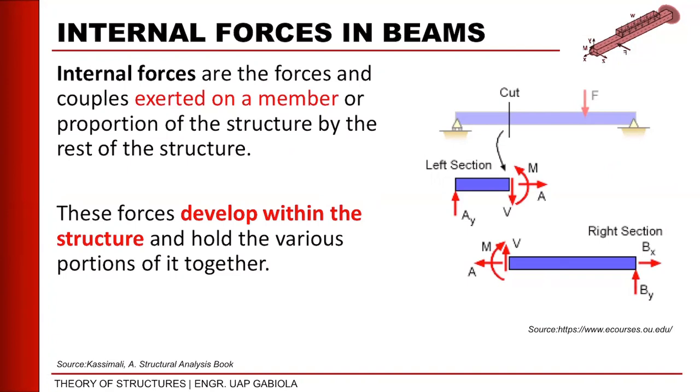So, kaya pag dito makikita niyo dito sa photo, if you cut the section along the beam, then in-expose natin, no? In-imagine natin na ma-expose yung left side and right section, we will see forces na lumalabas dun sa cut section natin. Those forces are our internal forces na tinatawag.